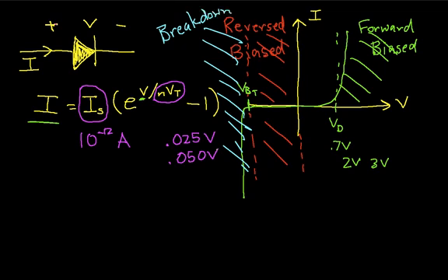And basically what happens is when the voltage across the diode becomes negative enough, then the diode actually breaks down and allows current to flow through it in the opposite direction to which current normally flows. In most diodes, if you get breakdown, it's catastrophic in the sense that you'll destroy the diode.